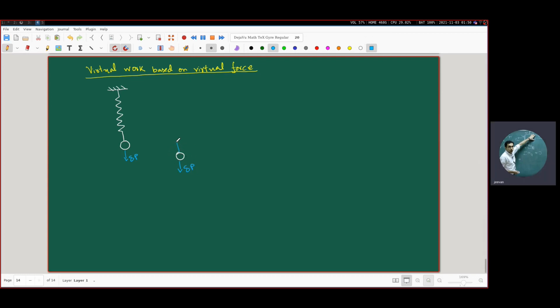Correspondingly, you will have a counterbalancing force, specifically a counterbalancing virtual force delta F, and you are going to obtain for the spring the same kind of situation like before. Okay, please understand that I'm trying to draw the same kind of spring that I have drawn on the left hand side, and you will have a force like this, delta F in the downward direction.